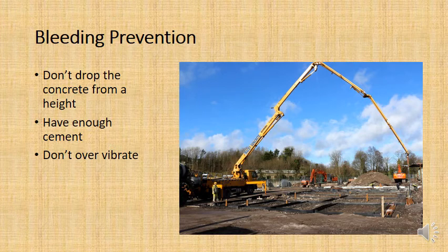One of the great things about concrete pumps is accessibility. Places which were a little bit hard to reach from the roadside, and where it was hard to get the concrete to, you can now put the pipe right above where it needs to pour. And so you never need to drop it from a height. Concrete pumps are great for preventing segregation and bleeding.